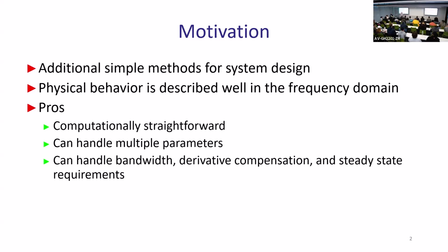So bandwidth is defined as minus 3 dB after the flat part. When you get to the down 3 dB, the width from 0 dB, from 0 hertz to that point is the bandwidth of the system. Which means if Bode falls down later in frequency, this is broader bandwidth of the system. If it is like a low pass, which is cutting here, this is narrow bandwidth of the system.